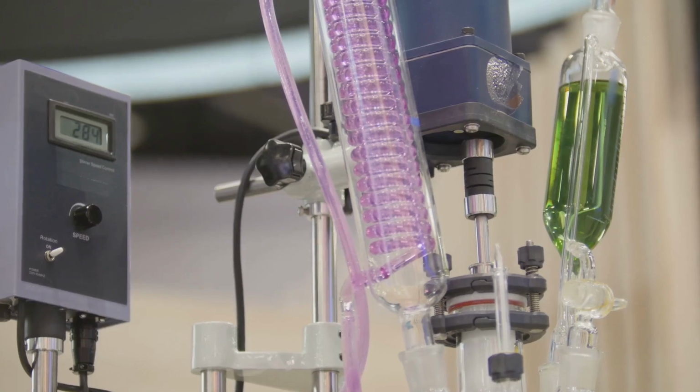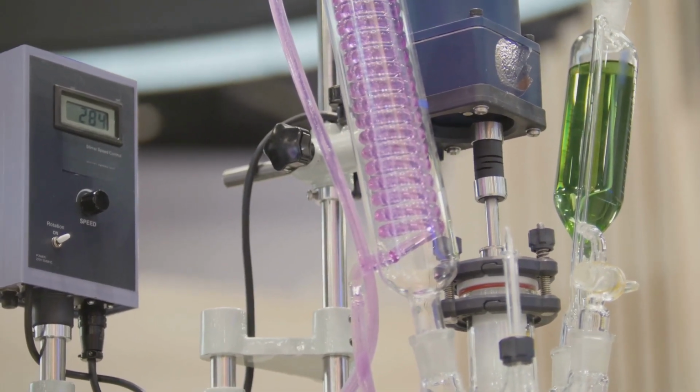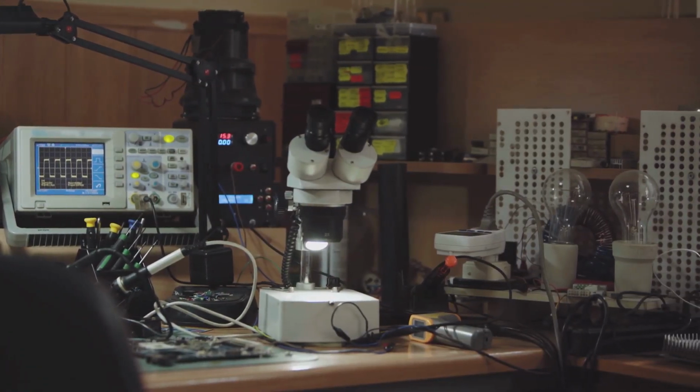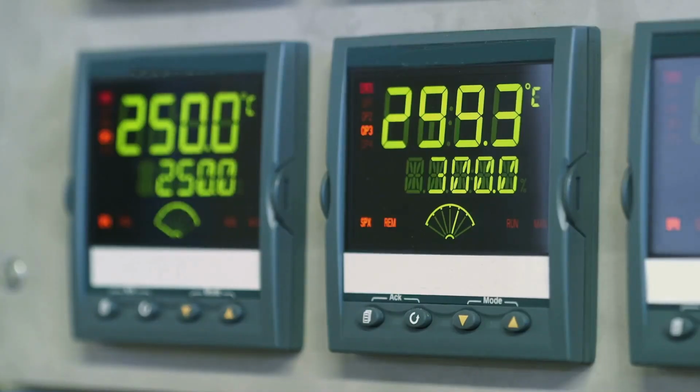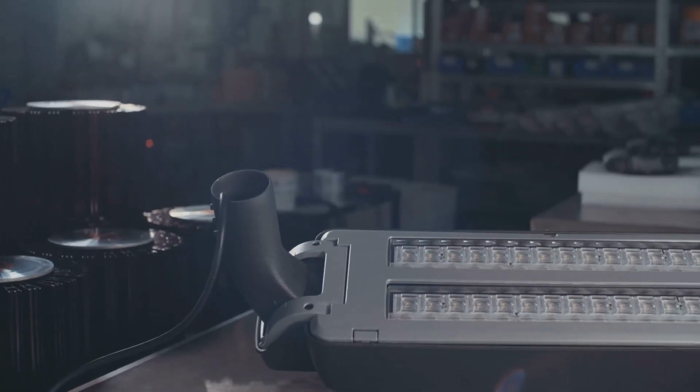Before adjusting PID parameters, it's crucial to lay a solid foundation for successful calibration. This involves understanding the system and gathering the necessary tools. System identification: gain a thorough understanding of the system's dynamics, response time, and any dead time or lag. Data acquisition: monitor the process variable, PV, and the controller output using sensors, data loggers, or software interfaces.